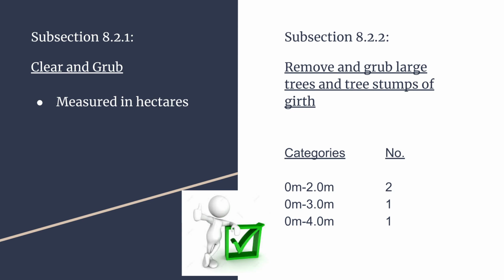Because the total area to be excavated is of a substantial quantity, the site clearance work shall be measured under Clause 8.2.1 of the SANS 1000C rather than Clause 8.3.11 of SANS 1000D. The total area to be cleared has been measured as 3 hectares, therefore the project's large scale justifies its placement in SANS 1000C.